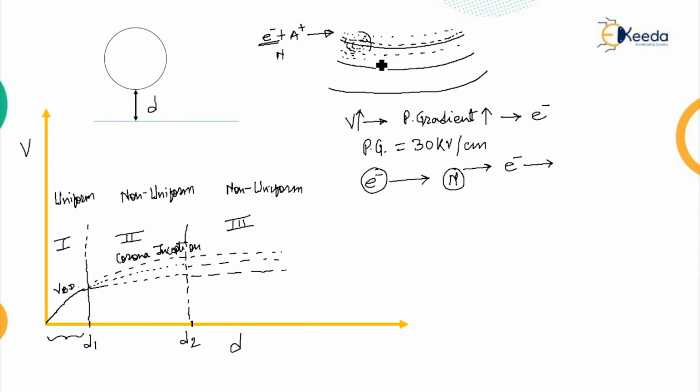Now as the gap between the conductors of the transmission line is completely filled with the electric field and ionization, there are chances of formation of the corona surrounding the conductors, and maybe also a spark between the two electrodes. So there is a need to maintain a sufficient gap between the two electrodes. And whenever we have corona formation, it affects the transmission line life, as well as causes power loss.